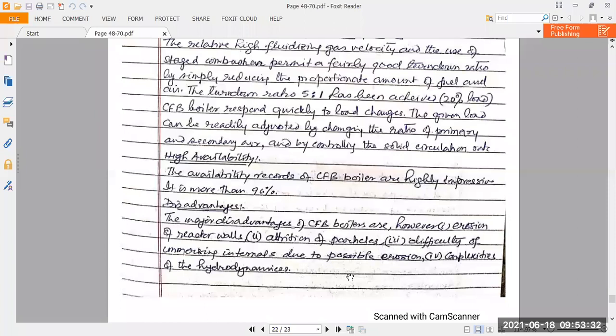Next we are going to the supercritical boiler itself. With PC technology, the once-through boiler is the only type suitable for supercritical pressure, because there is no latent heat of vaporization involved, and the water, on being heated at constant supercritical pressure, suddenly flashes into vapor. There is no saturation point temperature as such.